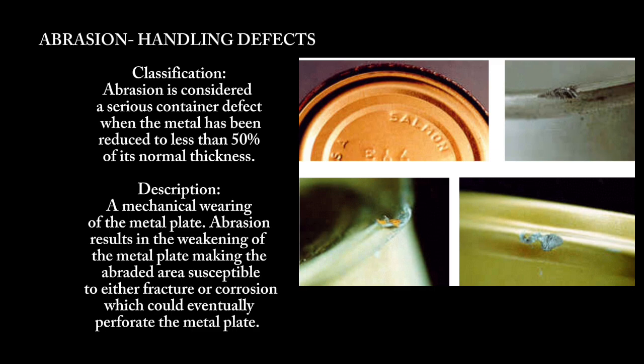So the common sources of this are moving cables or metal conveyors. Abrasion can occur when cans are moved along conveyors that rub against them, whether they are empty or filled. Another is contact with stationary objects with sharp parts. Cans may experience abrasion if they are moved against rough or damaged surfaces, such as when they are loaded into baskets with sharp edges or rust.